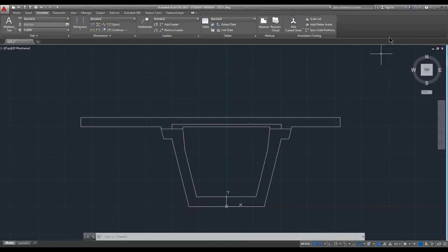The reason why arc, spline, those types of non-linear CAD elements cannot be imported into Civil is because FEA programs don't really have such elements as their basis. FEA elements run based on node, beam element, which is straight, and also plate or solid element. And none of them are equivalent to circles, arcs, or splines.